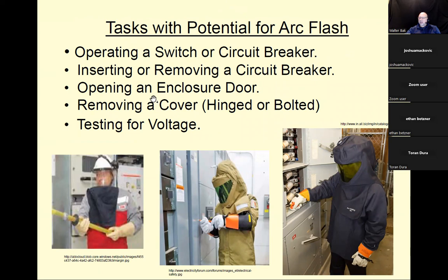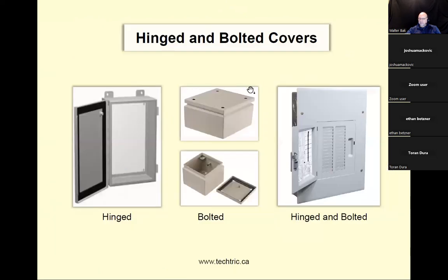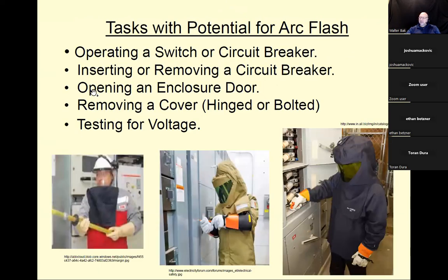Opening an enclosure door. So here are the doors: hinged, bolted covers. I just got some pictures. Here's a hinged cover, here's a bolted cover, and here's a hinged and bolted cover. So opening an enclosure door or removing a hinged or bolted cover can cause an arc flash.